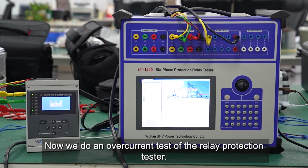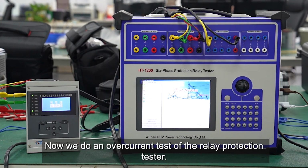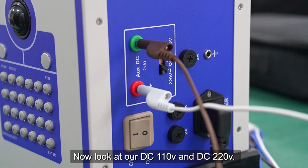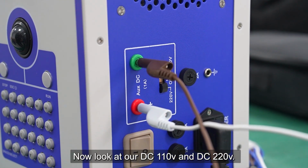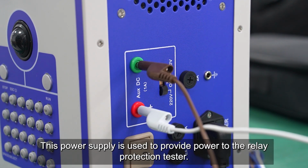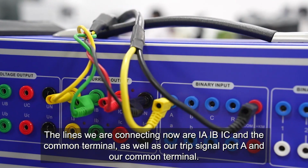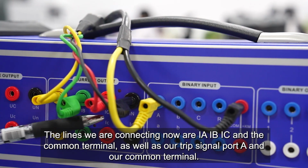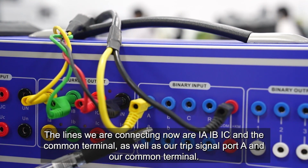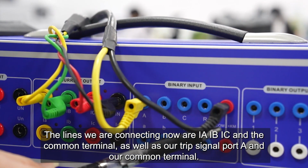Now we do an overcurrent test of the relay protection tester. Now look at our DC 110V and DC 220V. This power supply is used to provide power to the relay protection tester. The lines we are connecting now are IA, IB, IC and the common terminal, as well as our trip signal port A and our common terminal.